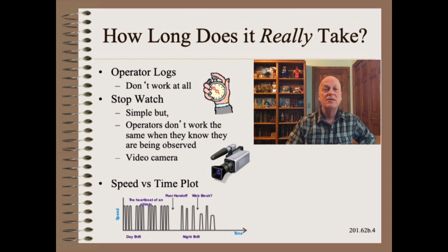Second, what happens during the down is not accounted for. Most importantly, the operators may not attribute the cause to their own negligence, when that may indeed be the cause on occasion. A brute force method would be to go down to the machine with a stopwatch and a clipboard. However, it should not be surprising that the operators might speed up or slow down, depending on what answers they want you to get. You could record machine activities with a video camera, but the operators might find that intrusive and offensive.